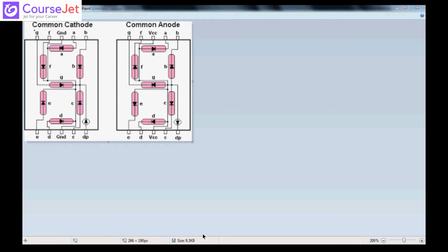One minute, I'll just show you. When you say 5 by 7 LCD, it will have something like this. This is 16 by 2 LCD. That means in each line you can display 16 characters. 16 by 2 means 2 lines, each line 16 characters.